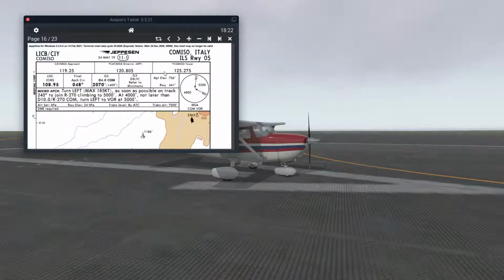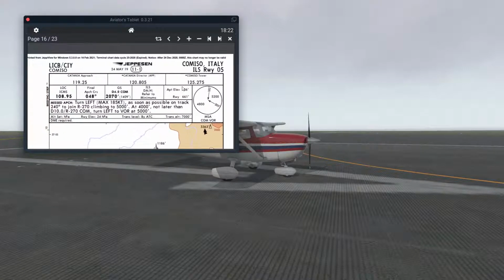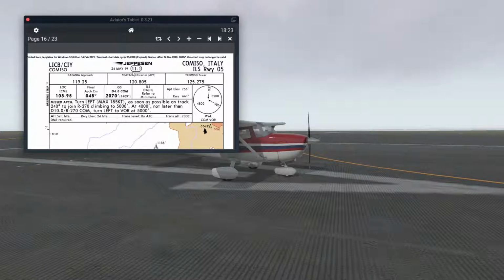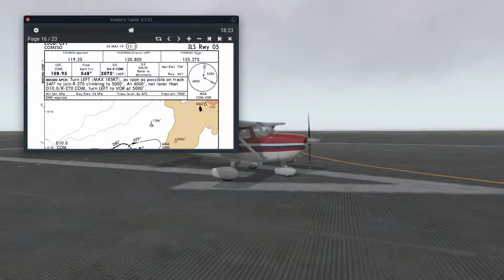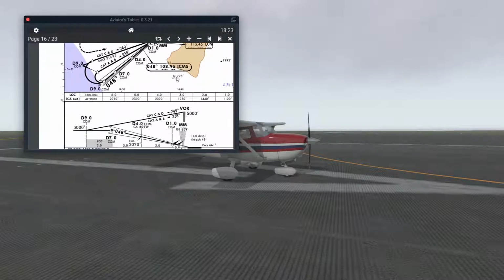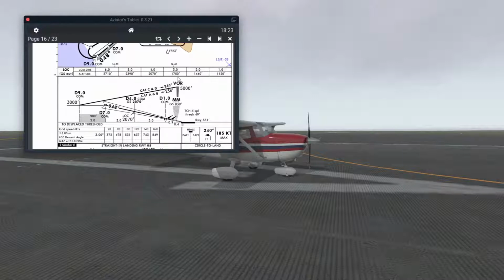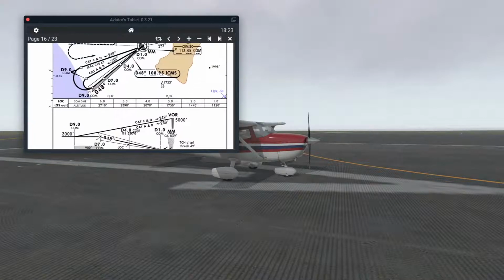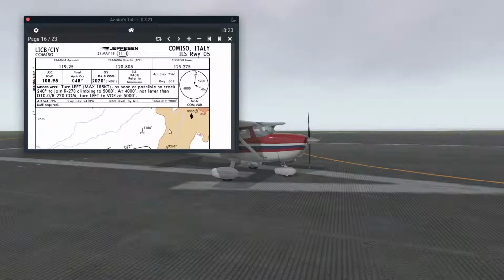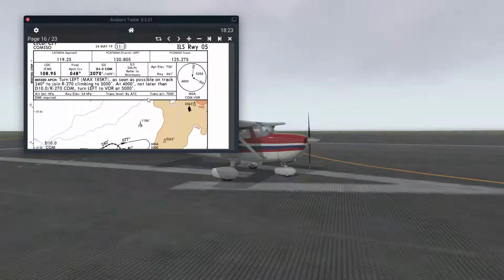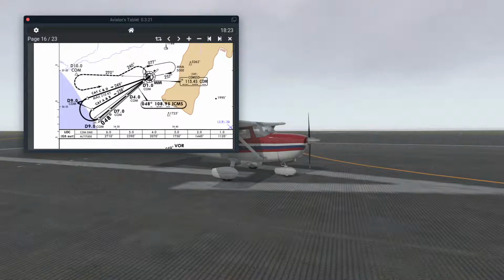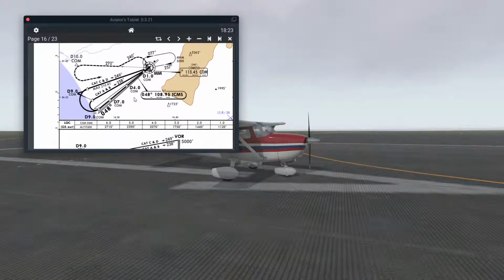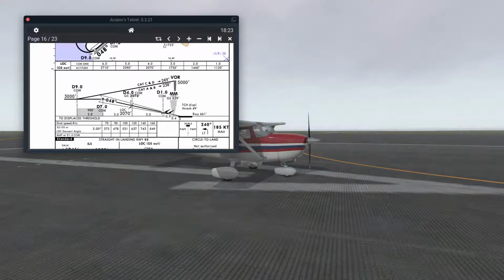If we can return back to this chart with the chart index 11-1 for ILS runway 05, as you can see, this is a 3D approach with the ILS navigation system, which gives us the localizer as lateral guidance and the glide slope as vertical guidance.